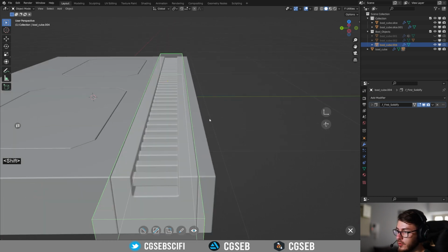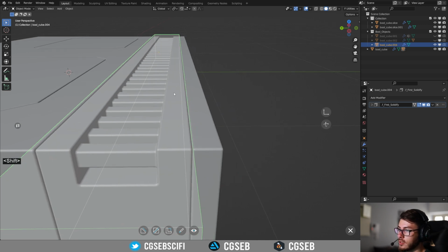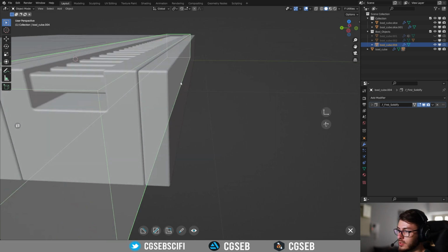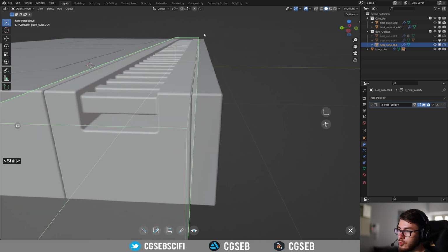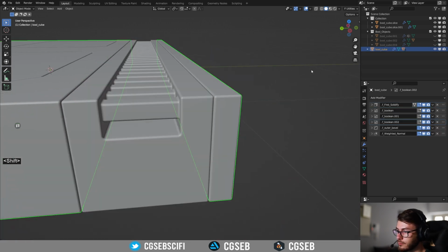Notice that every time you make a floor as a separate object, you always want to keep a space between the details that you add on the side and the limits of it, because you will have your wall that will go on it. So you always need to keep a margin between them. This is important.